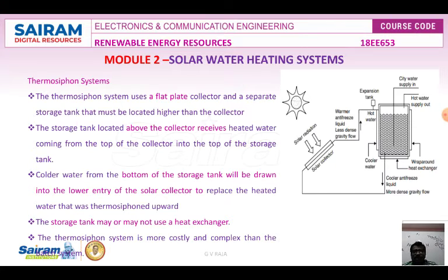The thermosiphon system is more costly and complex than the batch system. It is best to use an indirect system, one that uses a heat exchanger, because in case of rainy season or no sunshine, at that time also the water will be kept in heated condition.